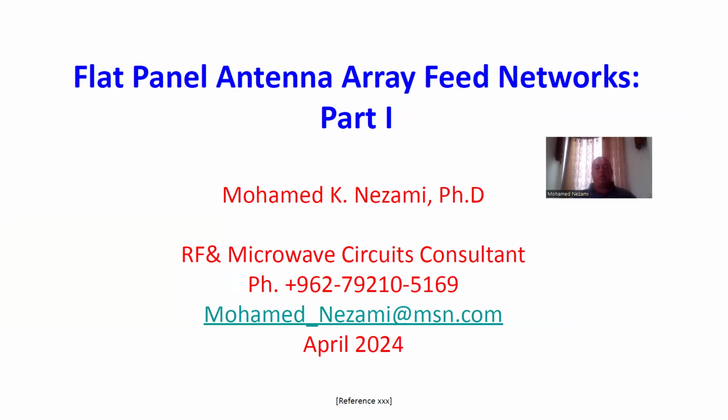So we need to design a few cells and then just copy and paste all over. But they involve either Wilkinson power splitters or T-junction dividers, mainly T-junction dividers. I would say almost every antenna aperture that I've looked at is using a T-junction divider.